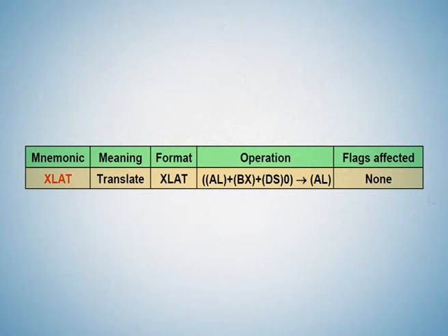The 8-bit register AL represents the offset of the element to be accessed from the beginning of the lookup table. The 8-bit address specified in AL restricts the size of the lookup table to 256 bytes only. The values in both BX and AL must be appropriately initialized before the execution of the XLAT instruction.